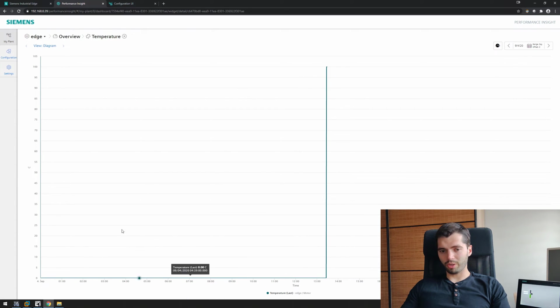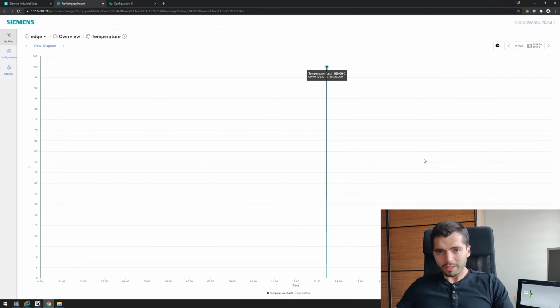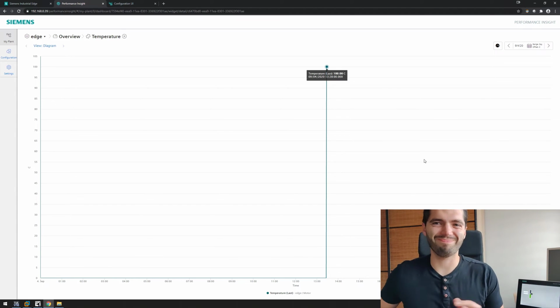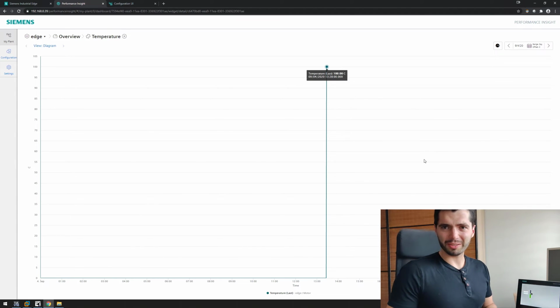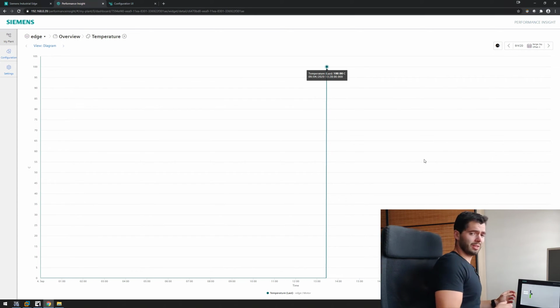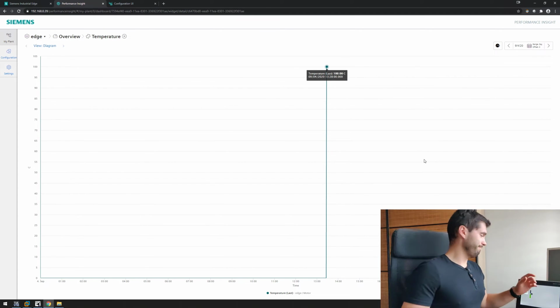So if this is 0 for you, what might be the case is you might have the wrong time settings on your comfort panel. And if this is the case, just go on the comfort panel and change the date and time. I will show you how to do it, but what I didn't do, I didn't include anything to disable the runtime. So, well, yeah.